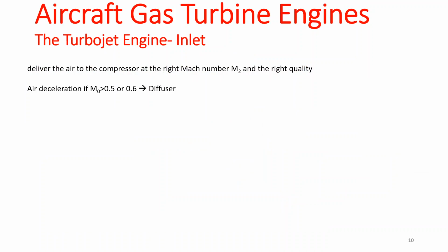Essentially it is charged with decelerating the air from the ambient Mach number to the compressor Mach number, as we said. So it is doing a diffuser job. It is diffusing the air.